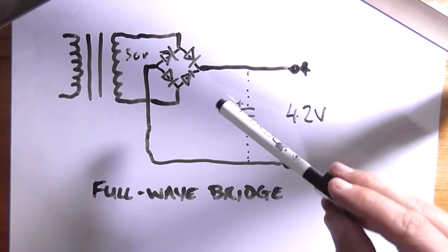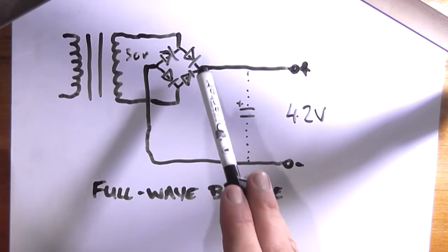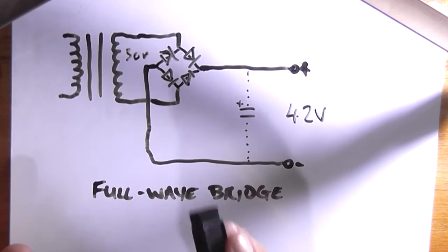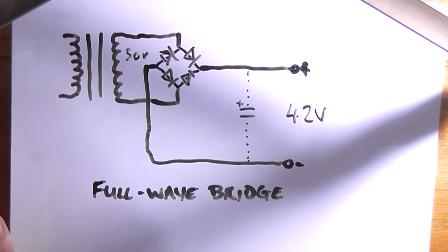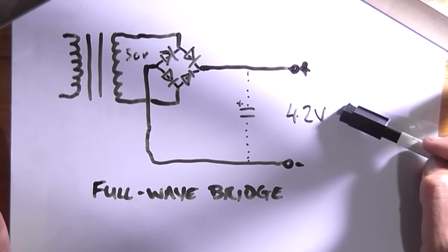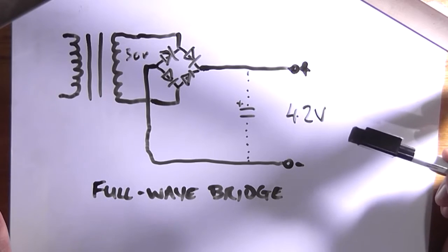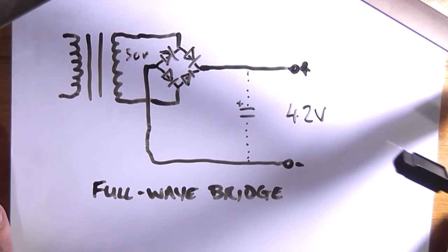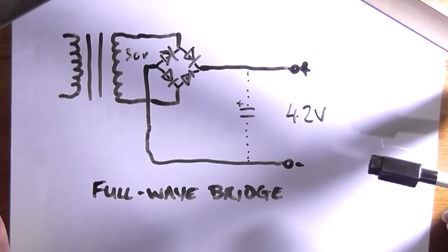Anyway, jokes aside, you'll often see it represented as this diamond with diodes going through it. And we'll stick to that one for now, and I'll show you the other representations in just a moment. The advantage of this is with a 30 volt transformer, even with a center tap in there, you would get the full voltage at its output of 30 volt DC without filtration and 42 volts with filtration. And you don't need a center tap, so that's its advantage. Plus, this particular rectifier can handle a lot more current than the two counterparts before it.